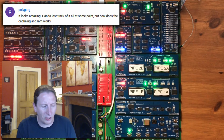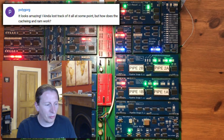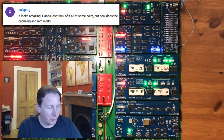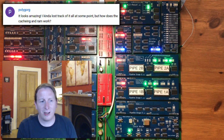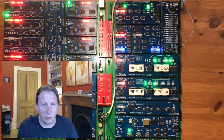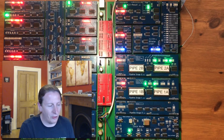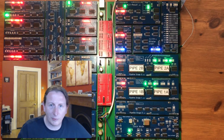The modified Harvard architecture, which is what you see in most modern processors, where you have separate code and data caches but driven by the same backing memory, is brilliant. But that would be a big implementation though, and in a component-wise circuit like this, you would spend so many chips trying to implement that it really wouldn't be productive. But if I ever do anything with FPGAs or anything like that in future, I would be very interested in exploring that. Hope that answers your question.